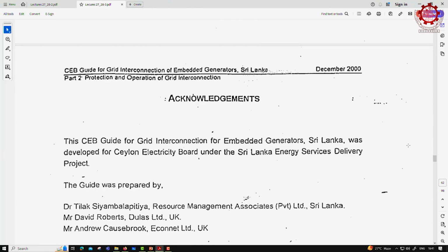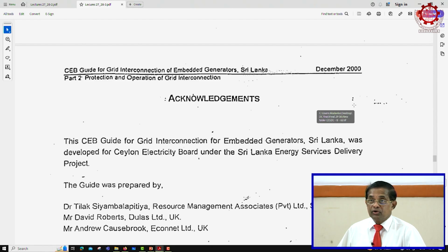Okay. So, I just wanted to expose you to the requirements of planning the entire electrical system and also grid interconnection requirements, right, because we are connecting a generator to a healthy grid that is available. So, our generator should not pose any threats to the healthy operation of the existing distribution network, because the distribution network is connected to the public, factories as well as households and other users. So, their safety is a prime consideration of the utility, right. So, if our system goes and disturbs them, introduces more harmonics, right, that is a problem.